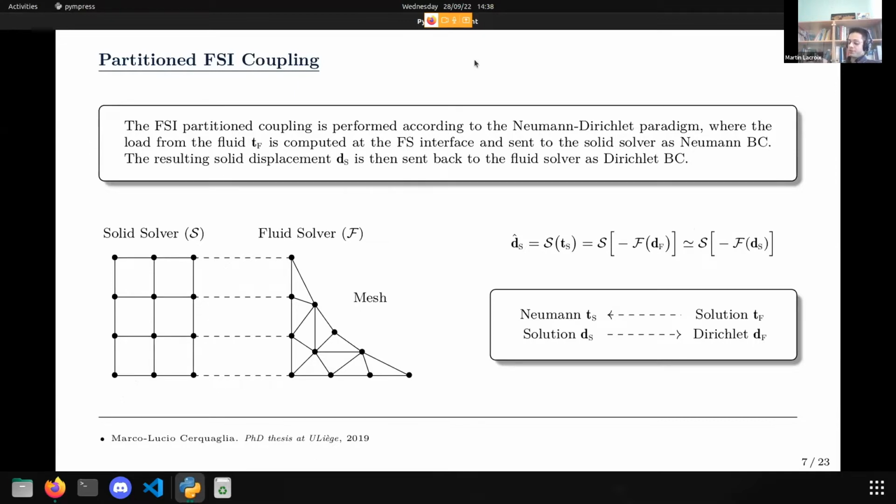But this is for the simulation of a fluid. When we want to do, for instance, fluid-structure interactions, we would also like a structure, and this is where we perform a coupling with classical finite element, because for the solid part, generally the deformation is not large enough, so we can simply use classical finite element. We will couple the two physics by what is called partitioned coupling, meaning that the fluid will be solved by a solver that is not the same solver as the one used for the solid part. And those two solvers will communicate between each other in order to perform this coupling.